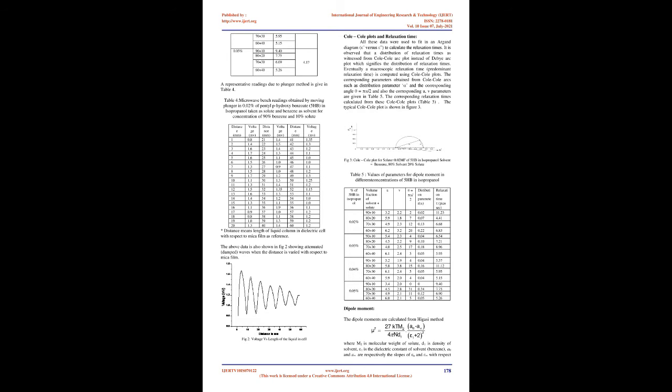Dielectric constant. The different concentrations of solute system, 5-HB and isopropanol, are dissolved in nonpolar solvent benzene at various volume concentrations. The dielectric constant of each concentration is measured at optical frequency, low frequency 1 kHz, and microwave frequency 8.83 GHz at room temperature. The complex dielectric constant, epsilon star equals epsilon prime minus j epsilon double prime, in the X band, 8 to 12 GHz, microwave frequency region is measured by using the cavity perturbation and waveguide plunger techniques.